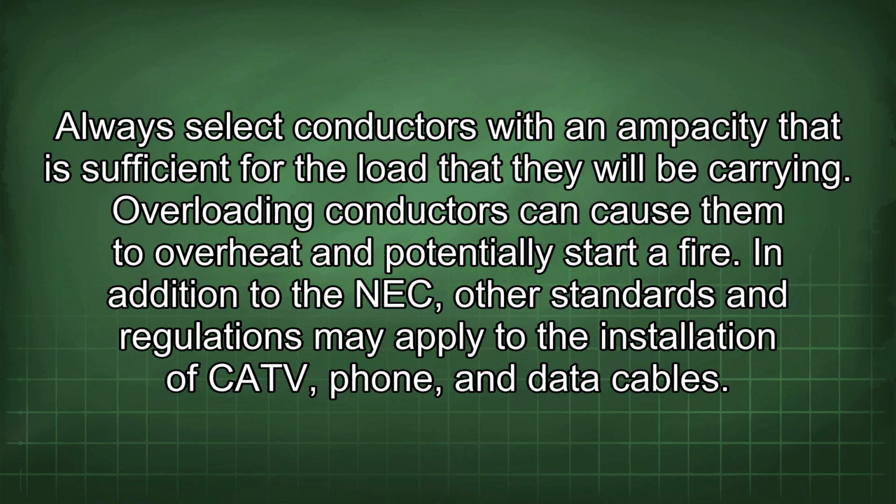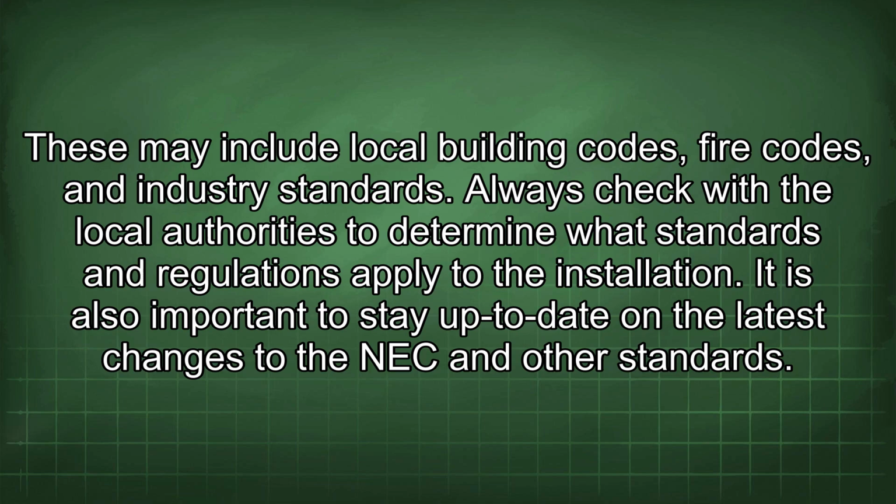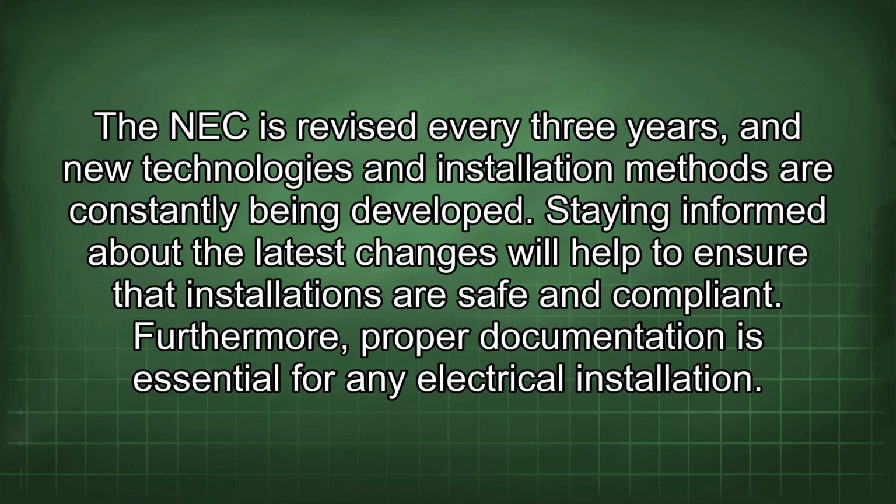In addition to the NEC, other standards and regulations may apply to the installation of CATV, phone, and data cables. These may include local building codes, fire codes, and industry standards. Always check with the local authorities to determine what standards and regulations apply to the installation. It is also important to stay up to date on the latest changes to the NEC and other standards. The NEC is revised every 3 years, and new technologies and installation methods are constantly being developed. Staying informed about the latest changes will help to ensure that installations are safe and compliant.